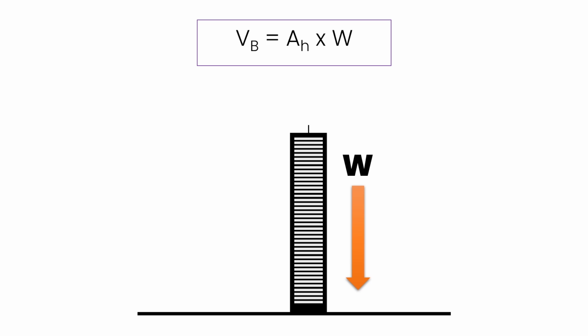When it comes to live load, we make an educated guess on the basis of probability as to how much weight would be available at that time. So say we have a live load of 4 kilonewton per meter square. We assume that during the earthquake, it is a very small possibility that the entire live load will be present. That is, the building would be occupied to its brim. And in that case, we slightly reduce the live loads. All in all, it will be a combination of the dead load plus the live load. And we'll be talking about that in a bit.